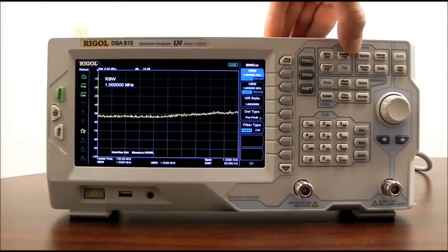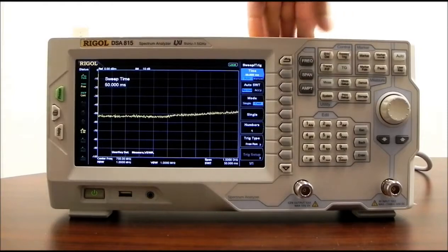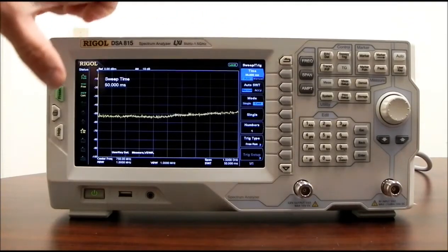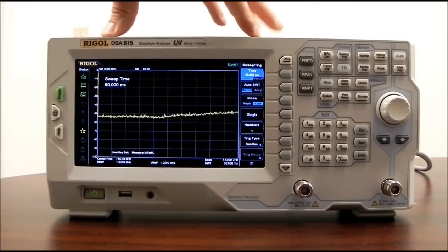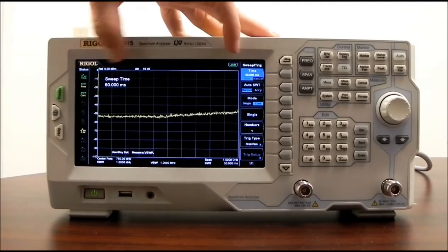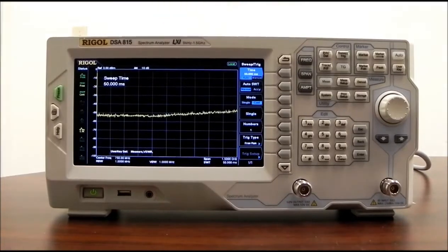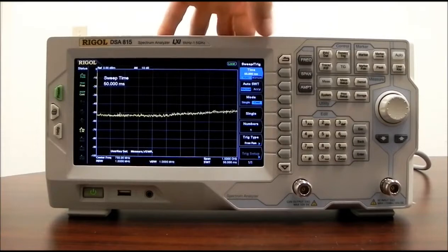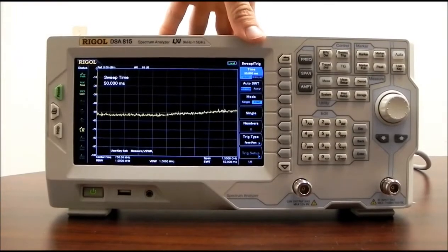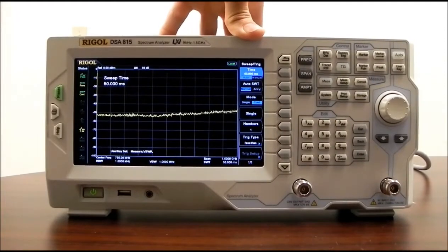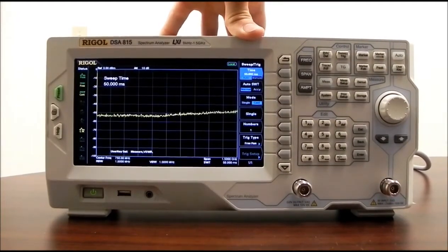And now let's take a look at the sweep and trigger. We can see that we can set the sweep time. Typically that sweep time is going to be on auto, based on the amplitude and the sweep configuration that we have set. The frequency range, the span, and the resolution bandwidth are going to determine that sweep time if we're in auto mode, and that's going to be calibrated. If we go to a manual mode, it's going to be uncalibrated because we're actually forcing the box to do things that it's not necessarily optimized to do in a calibrated sense.